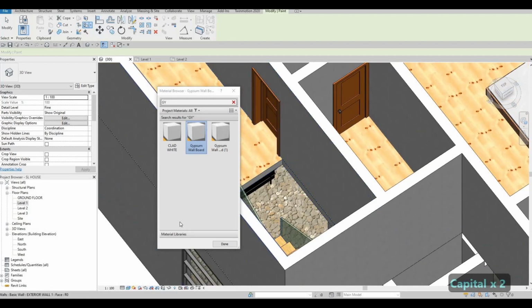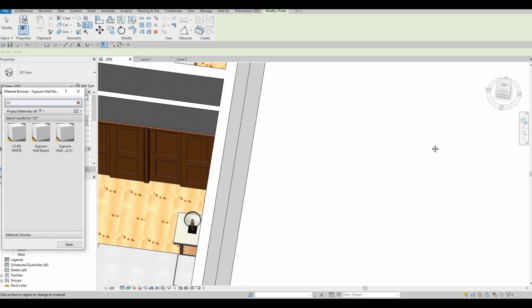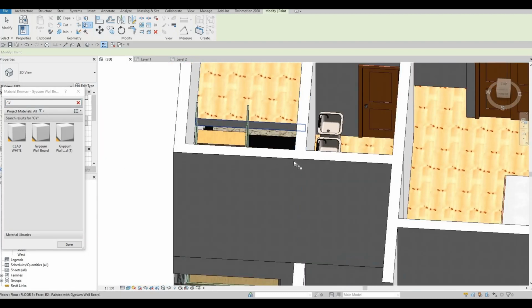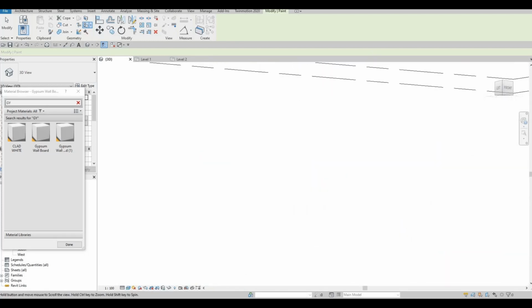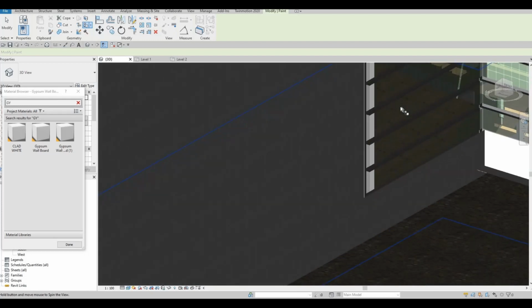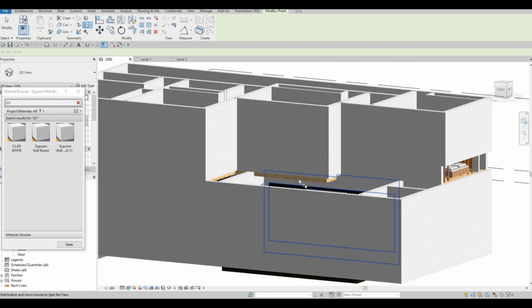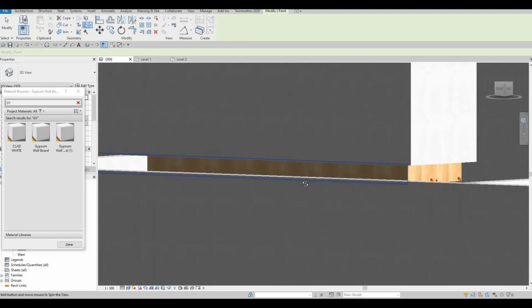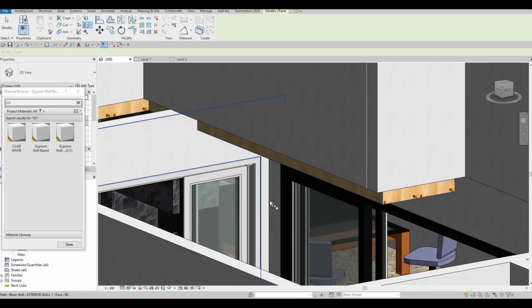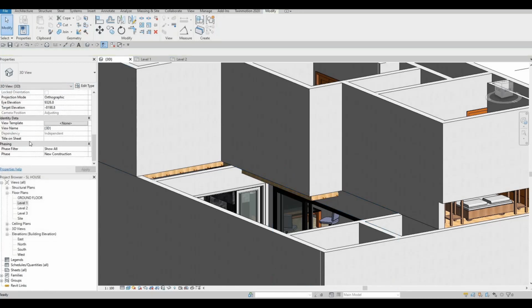So now that one is, so let's just put this one on the side. So that one is fixed, and we need to fix the one and below for the ceiling, because it's still showing on that one. So in order to show that, what a better way to do is to do a section, or we could do a section box.